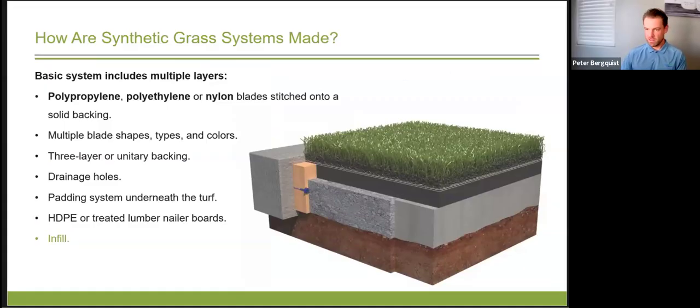What exactly does infilling mean? The turf has a topping made with resilient material sprinkled between the blades in order to ensure the blades remain stable, uniformly spaced, and resilient. Some examples that you'll see in the field are silica sand, which is the cheapest option, usually naturally occurring quartz. Performance sand, which is acrylic coated, helps resist compaction and is usually infused with antimicrobial protection. And then you also have crumb rubber, which will help lower initial safety testing scores, but it compacts over time and tends to be hotter. So that's definitely a factor in areas where heat is a concern.